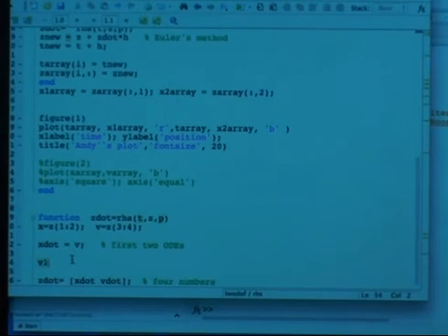Well, we have v1 dot came from some big expression divided by m1. And m1 we'll assume is called p dot m1. And now what was that big expression for m1? It was T2s plus T2d minus T1. I haven't figured out what those tensions are yet, but I don't want to do all that substitution in here because I don't want to make this thing too hard to read.